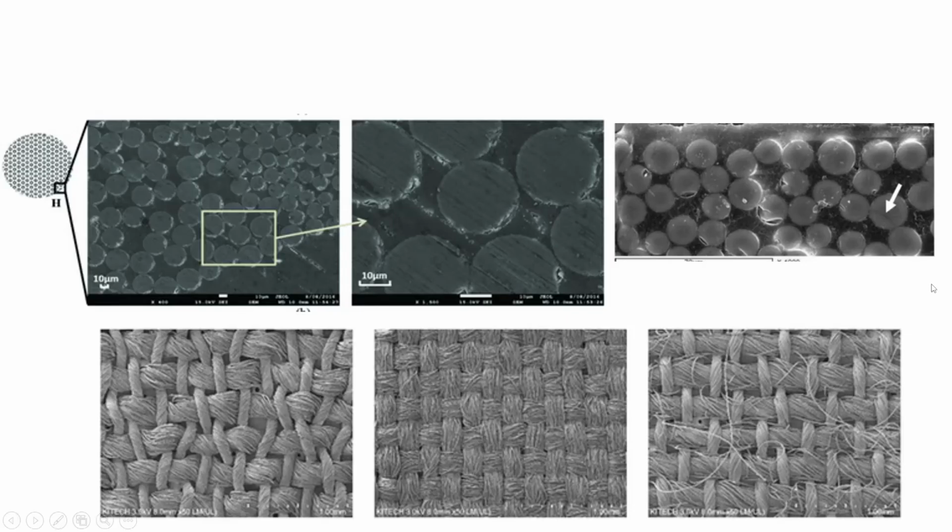Okay. So there is one sophisticated analytical technique which is known as FESEM. It stands for field emission scanning electron microscopy. In that, we first apply a very thin gold layer on this particular sample.